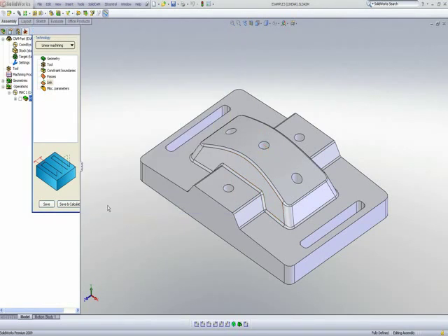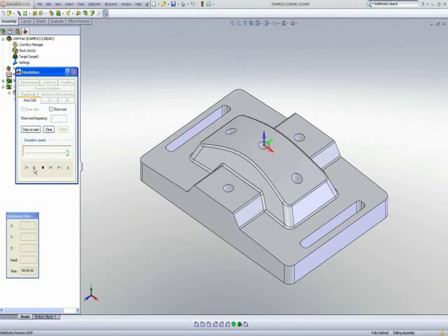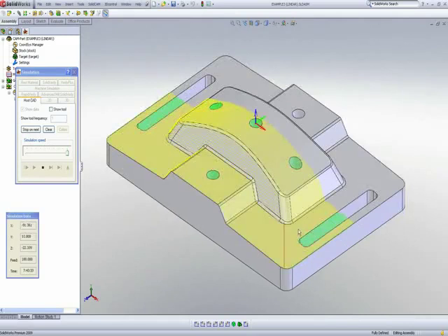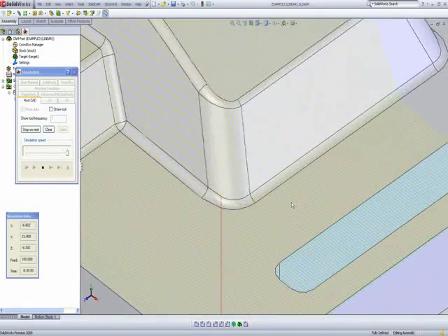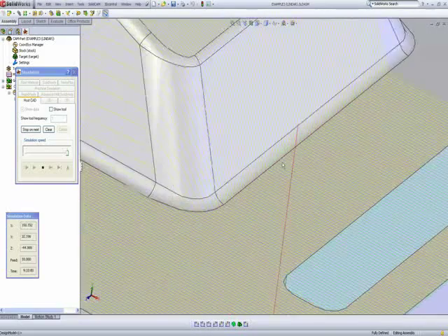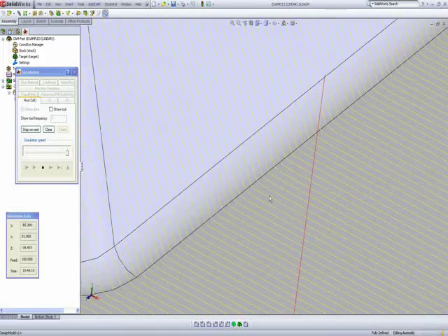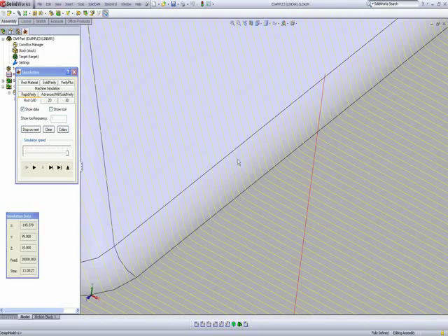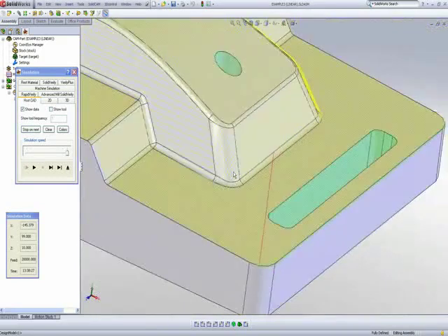and then do simulate, you'll note that the tool path works smoothly over the part, over these holes. Same thing over the slots. And what I'd also like to show you is that if I zoom in, you'll note that these corners, since I added a fillet, now have a tool path that works in a smooth radius fashion, allowing it to move swiftly without any sharp corners over the part itself.